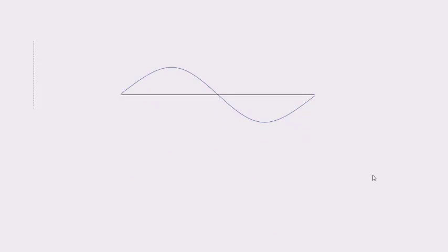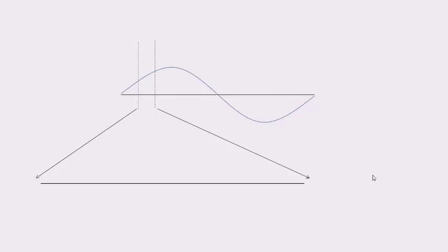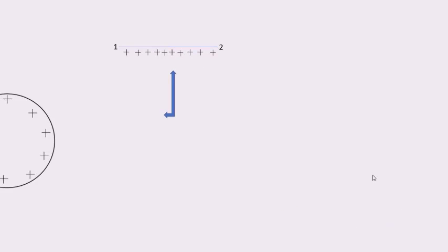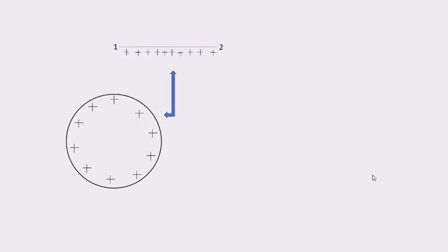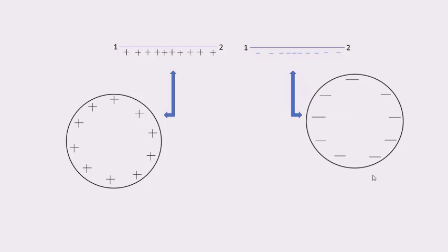Now consider that the wire length is a small fraction of the entire wavelength. And if this wire is excited with the same signal, then during positive half cycle it carries positive charge, and if the same wire is bent to form a loop, then the entire loop will carry similar charge. That is, here it is positive only. During negative half cycle, the wire is going to carry negative charge, and the loop which comprises the same wire is going to carry only negative charge.